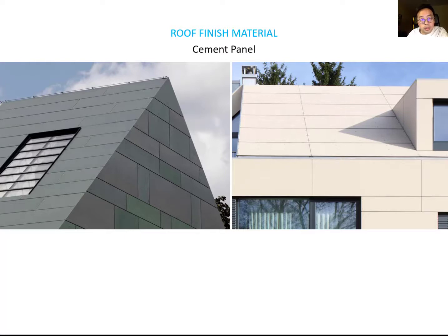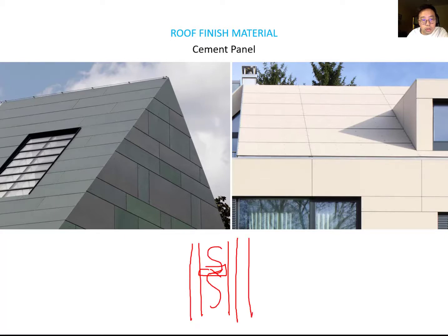It means the cladding system. You remember the cladding system. You can say the framing here, wall framing inside, and then sheathing. You can add in the insulation. Also you can add rigid insulation outside. And then you can add in the clip system from here to here, and this clip system holds the cement panel here and here.